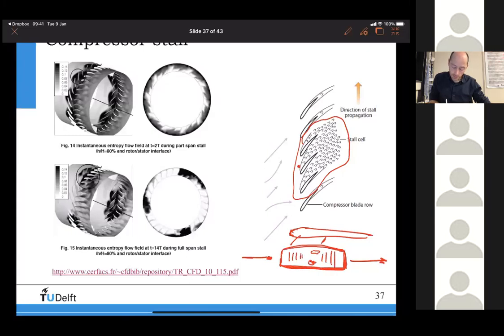The flow is supposed to go through the compressor, and the pressure is supposed to increase. Then you burn that high pressure air with some fuel, and you expand it in the turbine. But if you have compressor surge, all this flame can actually go out the front. There are videos online on YouTube; you can check compressor surge at takeoff, for example, because at takeoff you get quite high pressure ratios in the compressor, and then the flow can completely reverse, and the hot gases come out the front. That is compressor surge. But before compressor surge, you get the stall, and before stall, you get stall inception.